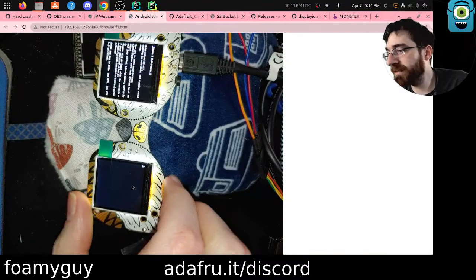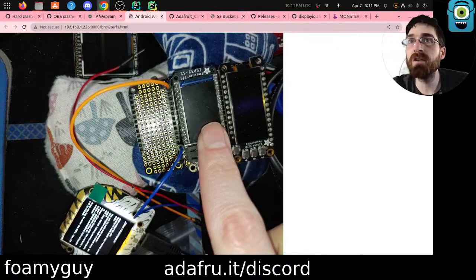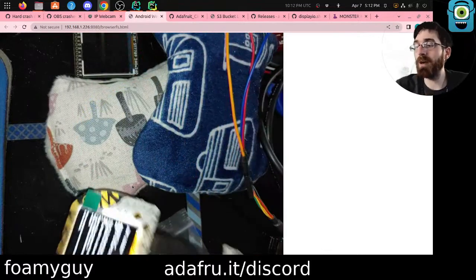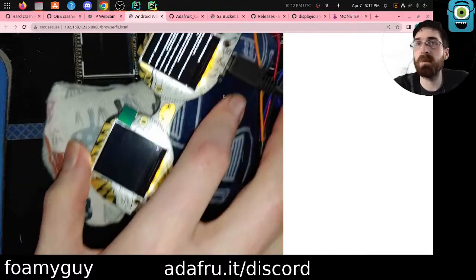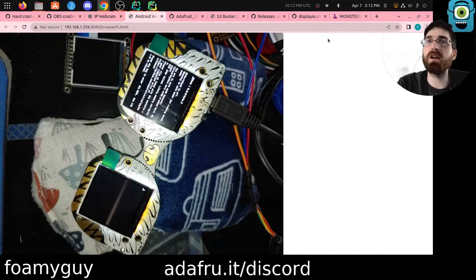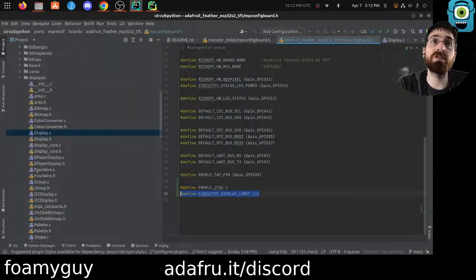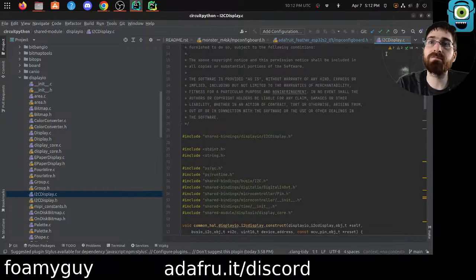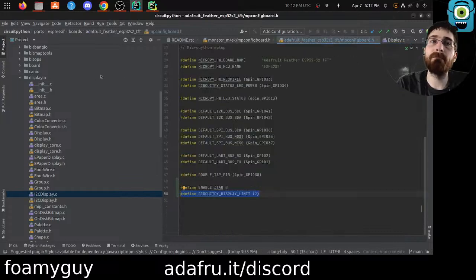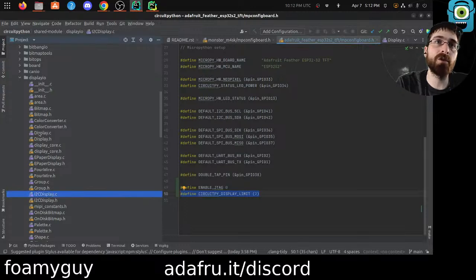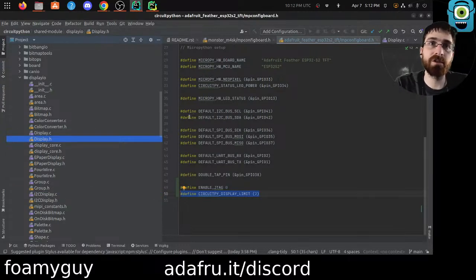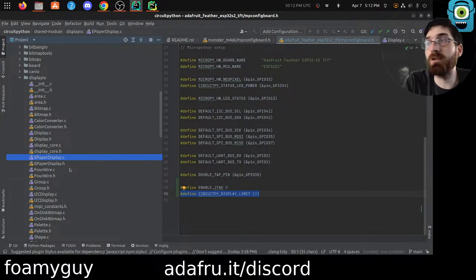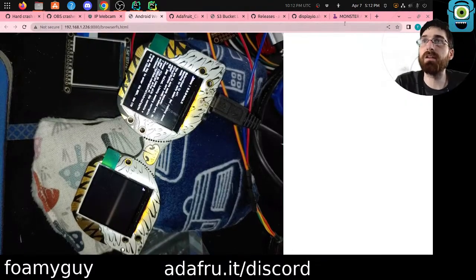On this device back here that I was messing with a bit ago, this is one display and one I2C display. An I2C display is a different object in the API, right? It's the same module, still inside display.io, but it's a different kind of display. I2C display here is its own class. So I have one I2C display and one regular display, and that is working for me. I believe one ePaper display and one regular display would also work, but I have not tried it.